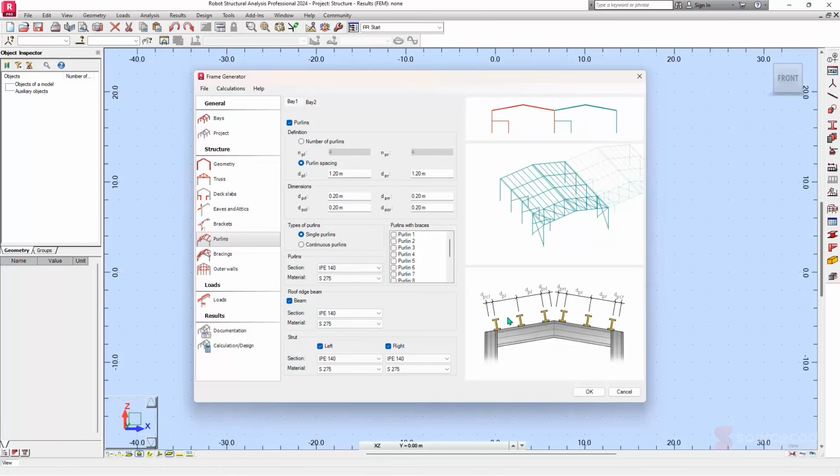In between each specific purlin, what will be the distance? So this is usually guided by the type of sheet that you're going to be using to install your roof. The PRL, which is simply the distance from this point here, which is a rafter, to the specific purlin, and also the PCL, which is a distance from this column to this specific purlin. And the same thing is repeated on this other side. So I'll just leave it as is.